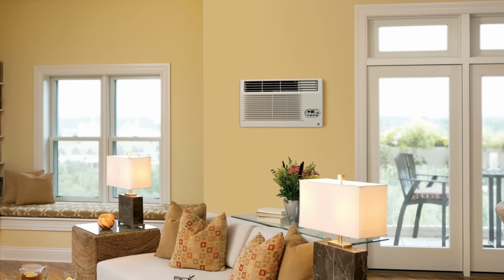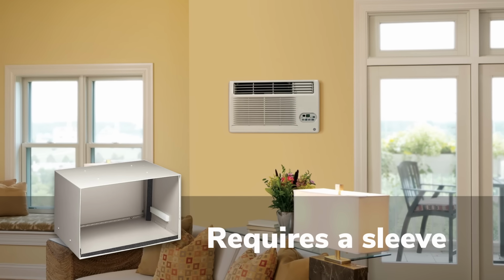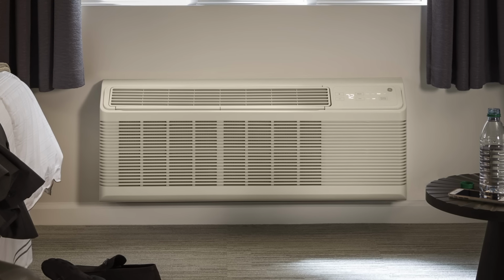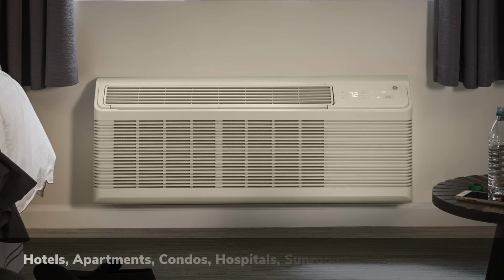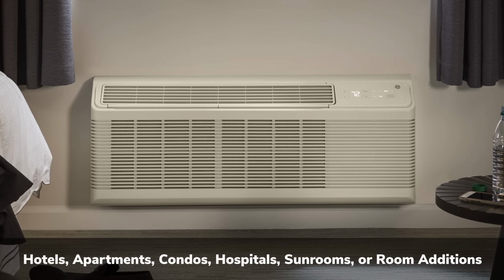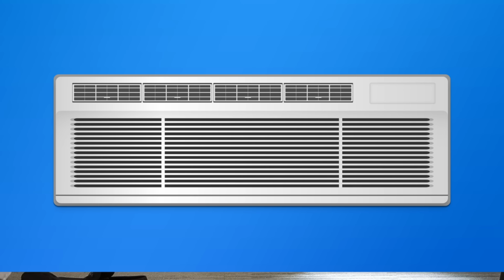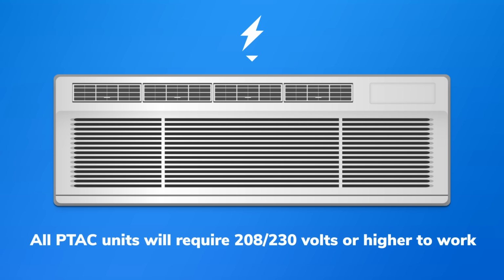They install through a wall of a building and require a sleeve. These sleeves are not included with the unit, but can be found in the air conditioning accessories category. PTAC ACs, which stands for Package Terminal Air Conditioners, are self-contained heating and air conditioning units that are mostly found in hotels, apartments, condos, hospitals, sunrooms, or room additions. Like wall ACs, they install in wall and require a sleeve and external grill accessory to complete the install. The main difference between PTAC and wall units is that all PTAC units will require 208/230 volts or higher to work.